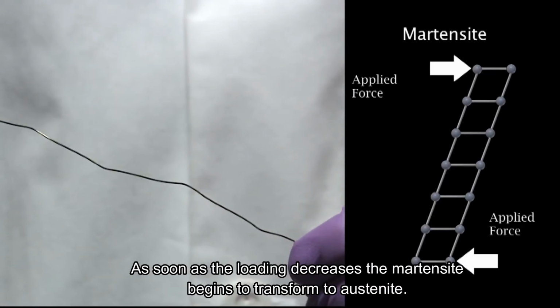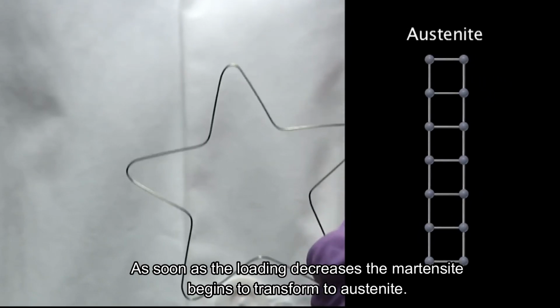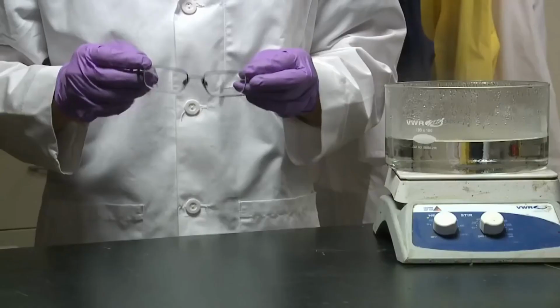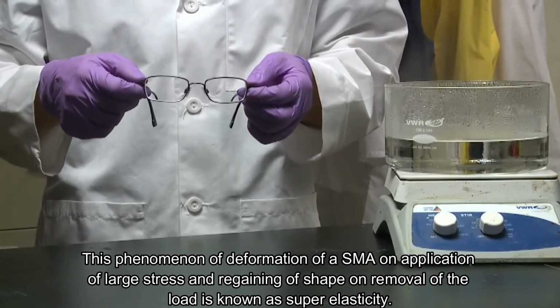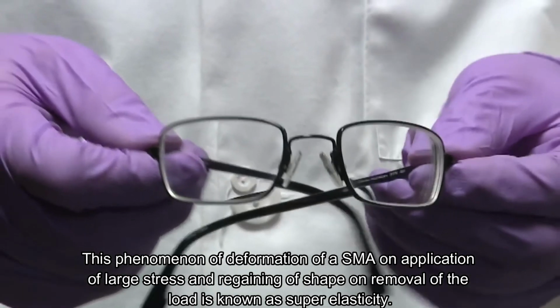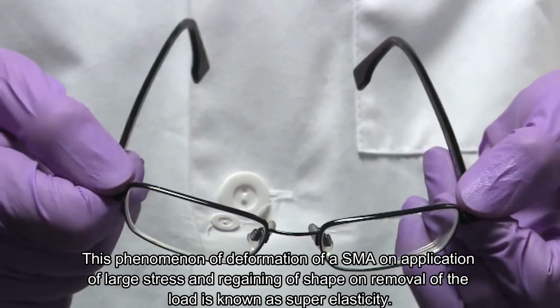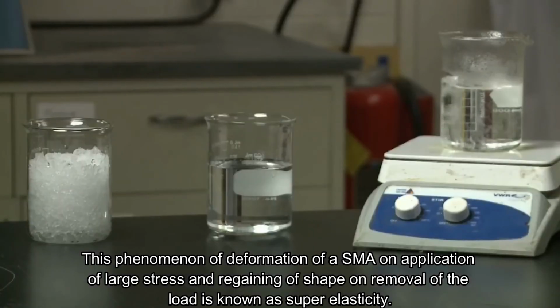As soon as the loading decreases, the martensite begins to transform to austenite. This phenomenon of deformation of a shape memory alloy on application of large stress and regaining of shape on removal of the load is known as superelasticity.